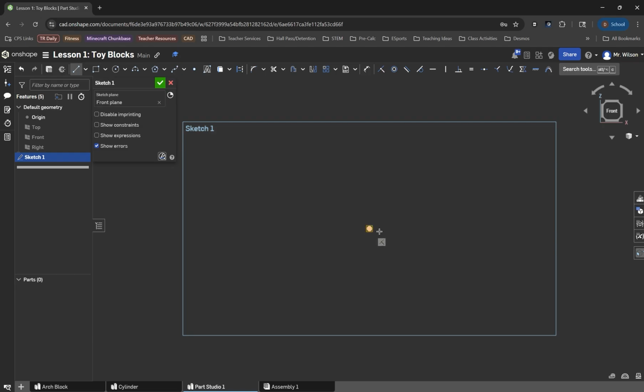You can start here and come out and then dimension your lines, or what you can do is use your offset constraints. So like vertical, then I can click here, come down and click my point here, and now I have my rectangular box that I can go, I want it to be 3 inches.